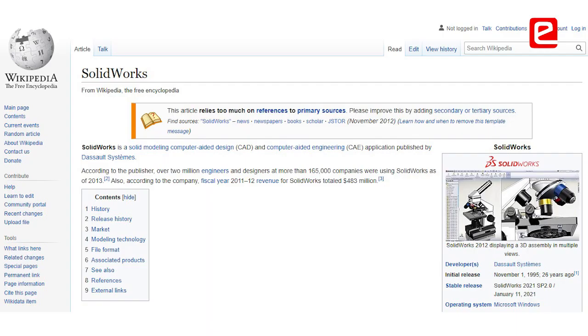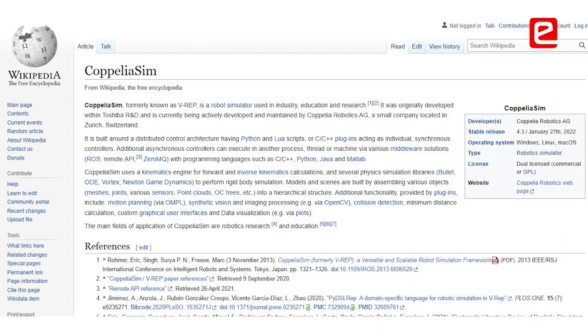Everything which we designed in SolidWorks, and after importing it into CoppeliaSim, one of the major issues we were facing was the vibrations of the parts, and the eYRC team had helped us. We didn't initially know that the inertia has to be above a certain level before the CoppeliaSim physics engine can properly solve the dynamics of the system.